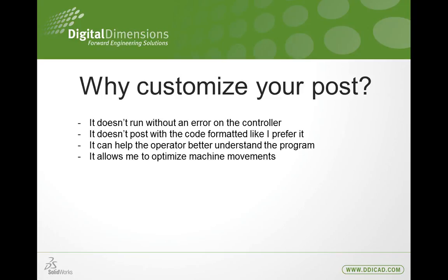And lastly, it allows me to optimize machine movements. And this is critical when maybe it's making an extra move between every tool change, and you start to realize after 1,000 parts, I'm wasting 10 minutes making this one move. Well, I can go into my post and customize it to do the moves that I see fit.